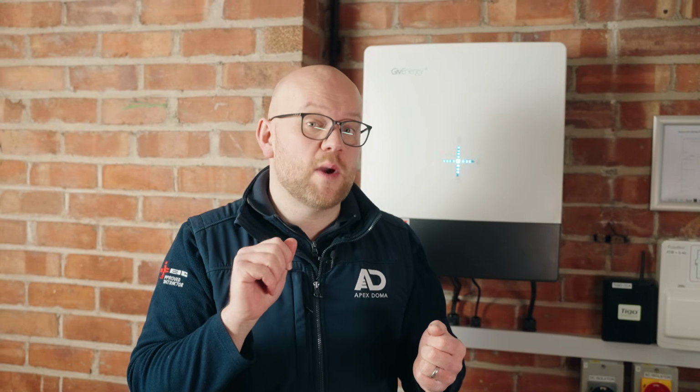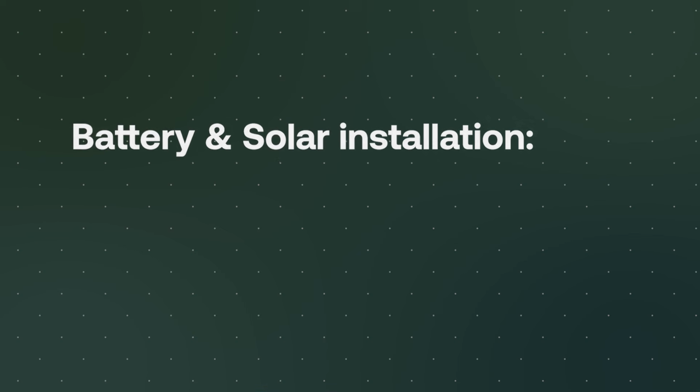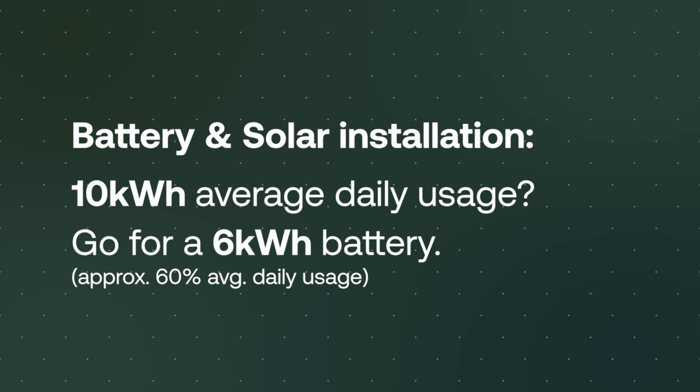But remember, you're now on a cheap night rate as well, because you're buying this energy in for cheap within the battery. And those night rates often last for 5 or 6 hours, with Flux only lasting 3, so this equation could change. So now I've got 5 or 6 hours, well, that's another 25% of my day usage, 2.5 kilowatts. So at that point, I actually only need a battery that's about 6 kilowatts in capacity to be able to buy enough on the cheap night rate to be able to last the full day with a little touch of solar and a little touch of that cheap night rate, thus bringing the cost of your initial installation right down.